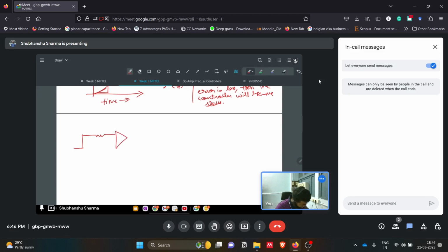That is simple. This minus plus gain, we can have this compensation of bias current. We have 100k at the feedback and 100k at the input. So this is acting as a proportional controller, a simple inverting amplifier with a gain of minus 1.